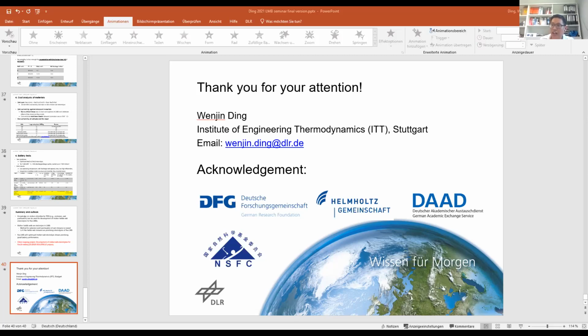And the second point is that when we have this alumina coating, we should pay attention to its long-time stability. For heat storage, we have a problem because the molten salt will change its temperature, and that means the coating will have thermal shock.